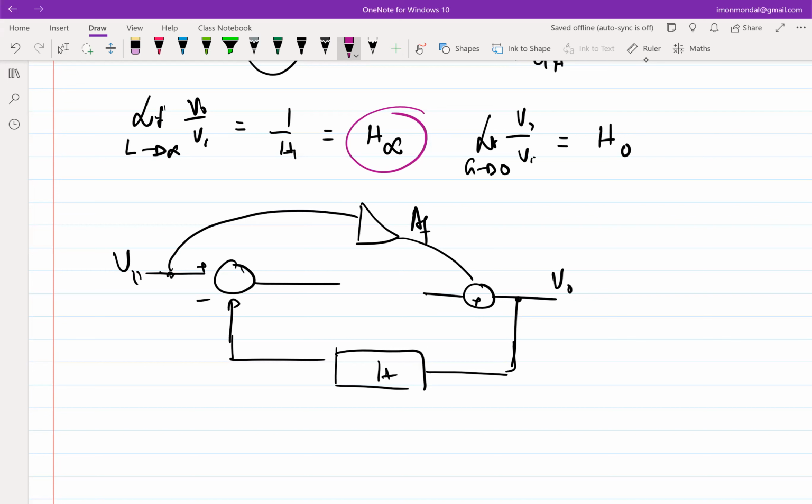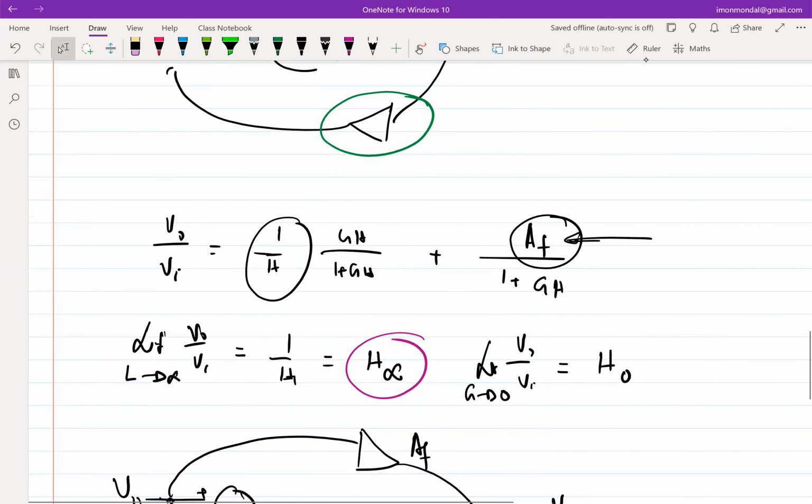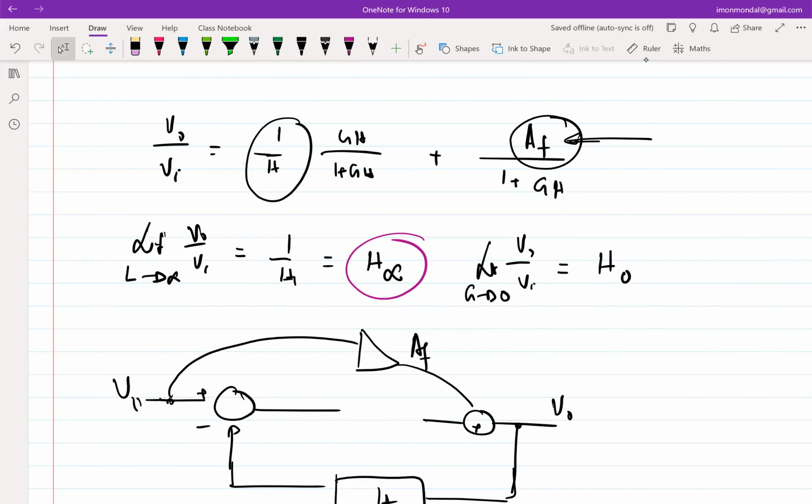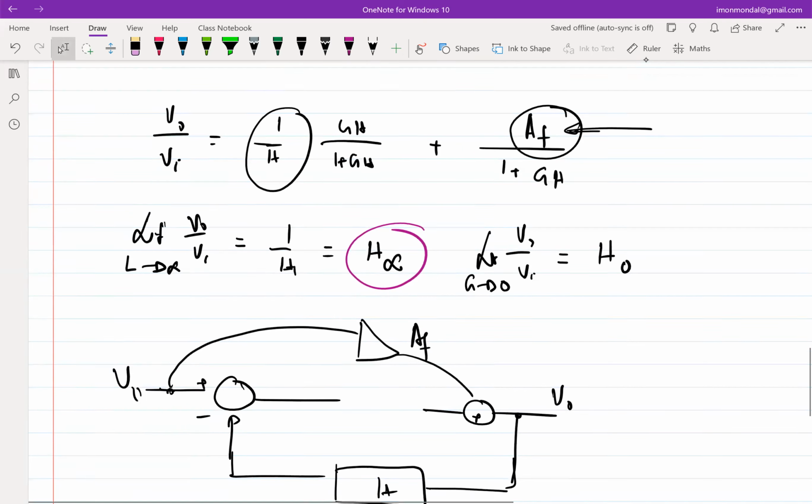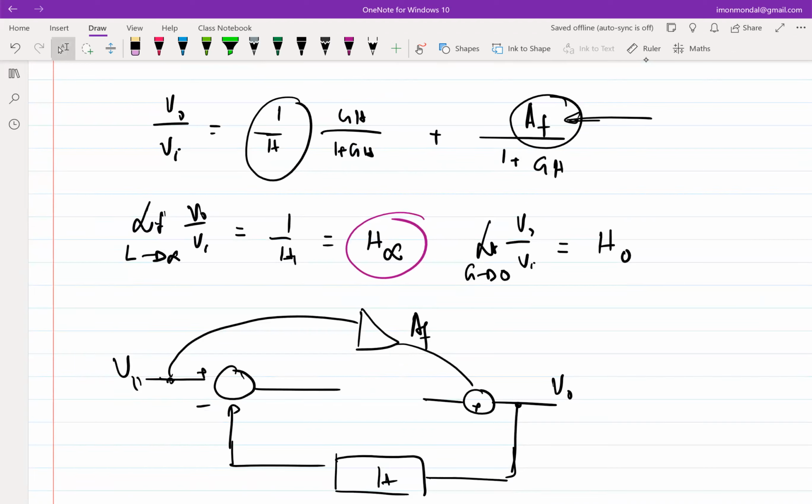Okay. So this is another circuit design hack. The reason we are doing all those things, and you might wonder why we are spending time on this, is that ultimately I can always write KVL, KCL and get a big expression. But the key thing is to figure out what to do with that expression. We don't want to write KVL, KCL all the time for every small thing. We need to look at the circuit and figure out if I can write the transfer function straight away with minimum calculation, right? So these are the ways of intuitively understanding how the network is behaving.